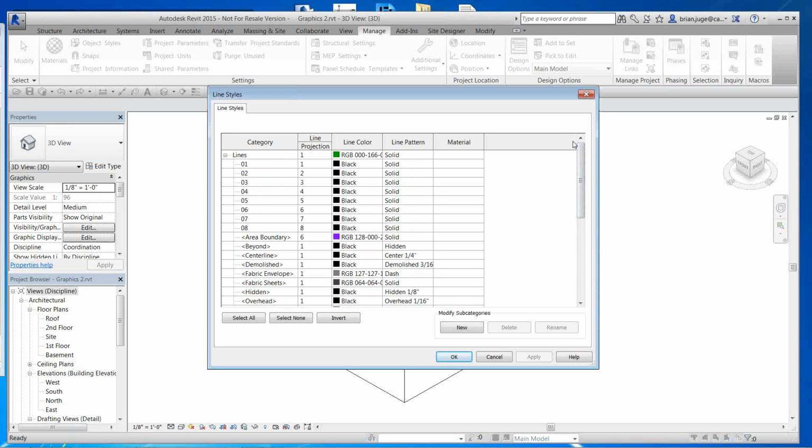The other thing to look at is, instead of going in and doing this thin line, medium line, fine line type thing that we do, what I've come into my template is I've set up the line weights and they're all based on the numbers. So as we come in here, an 01 is a 1. An 02 is a 2, and so on and so forth. And we could build that in here, and that makes it really easy for someone to understand what line weight they're picking.